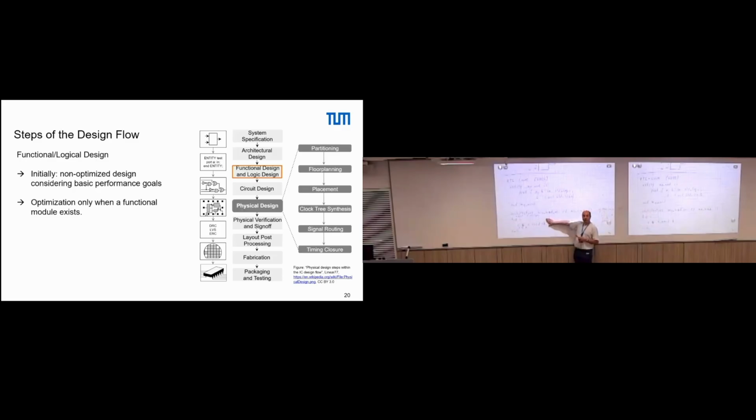What's here? Now we are in hardware. The things here are signals. So if we draw the logic of this diagram, we have a NAND gate. This NAND gate has inputs A and X, and output C. That's this line. And X is assigned to B, so X is connected to B. That's perfectly fine, because this is not a classical programming language. It's a hardware description language.